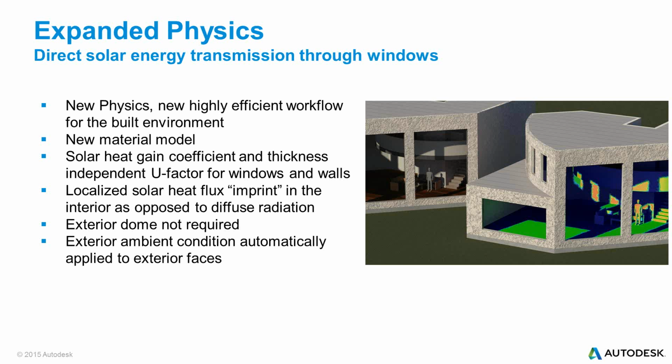So there's a new material model, and we call it solar wall or solar window, and it allows you to put in your inputs for the solar energy transmission, the data that you would get from a manufacturer. So instead of going through and making a material science project out of it, putting in wavelength dependent emissivity and all this kind of stuff for solar, what do the manufacturers put out?